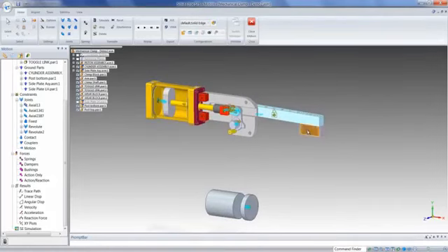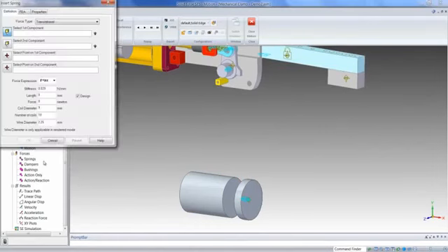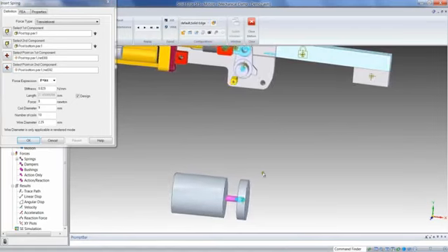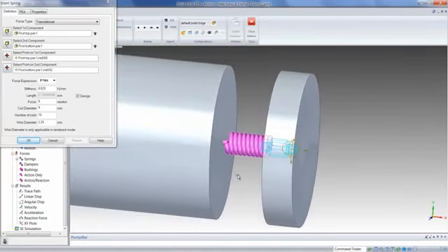Before we add the contact between this clamp pad and this top post, we'll go ahead and add a spring in between the top post and the bottom post. Simply click on the two components and then click on a circular edge for which to attach the spring ends to. Dynamic Designer will create a simple spring graphic. It is not a solid edge part.